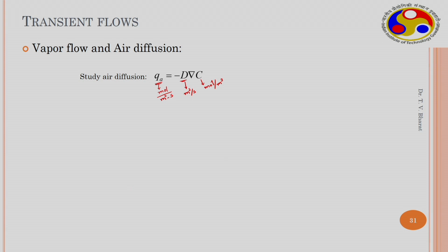Now, this equation has many applications, especially we discussed the axis translation technique earlier. In the axis translation technique, you have a high air entry porous disc which separates the water reservoir. So, this is the water reservoir.